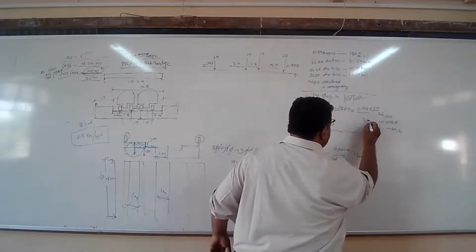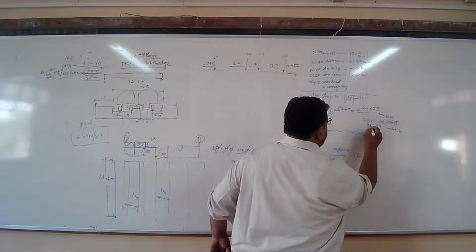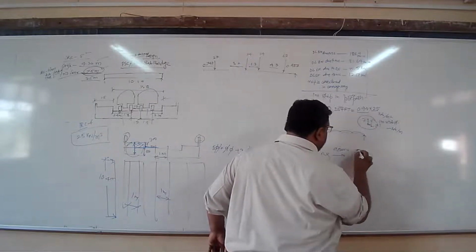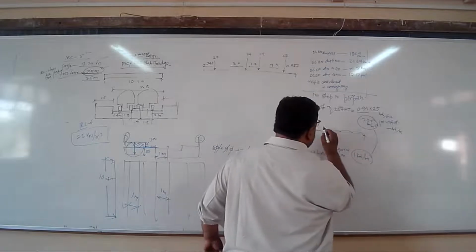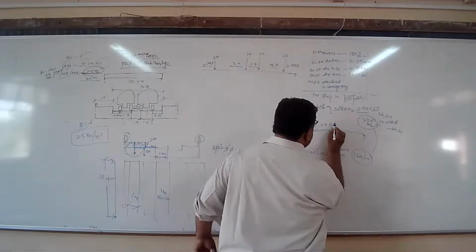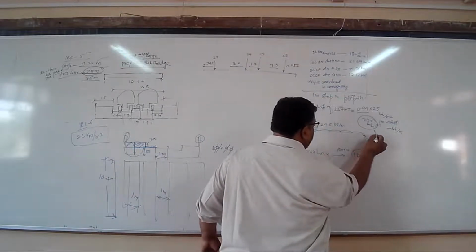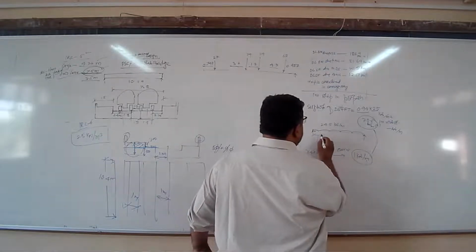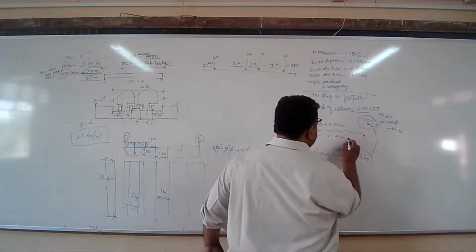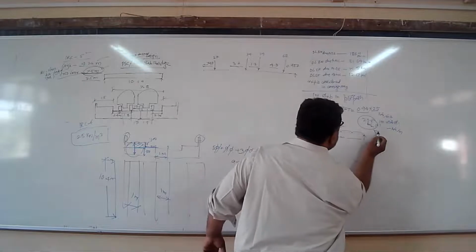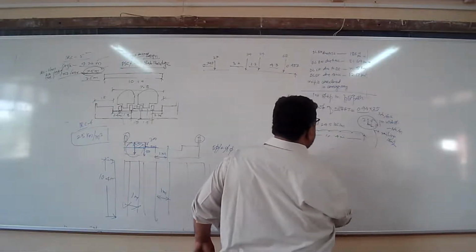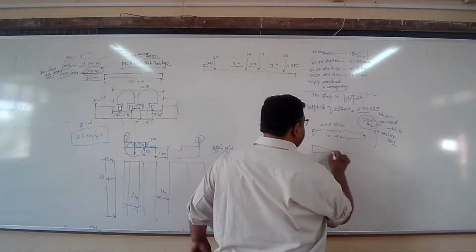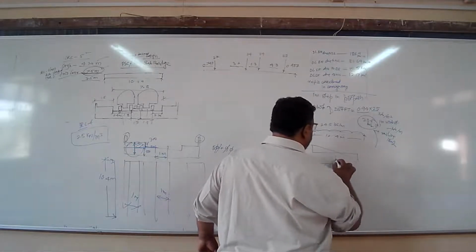So this is 23.5 kilonewton per meter. We will add this 1 meter value to it, so the total will be equal to 24.5 kilonewton per meter. The railing has been added here. The span is 10.4 meters. Now get this. This is the railing, 1 kilonewton. I have added it. So now here is the shape and here is the railing moment.